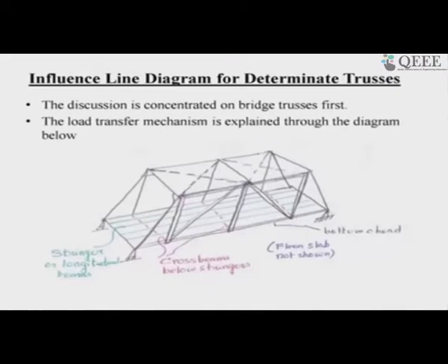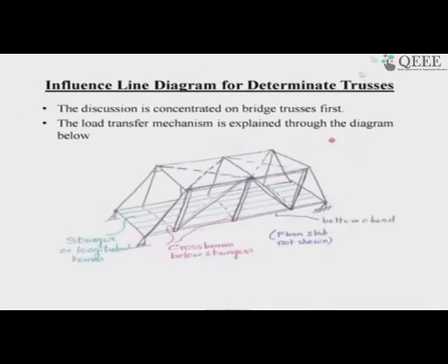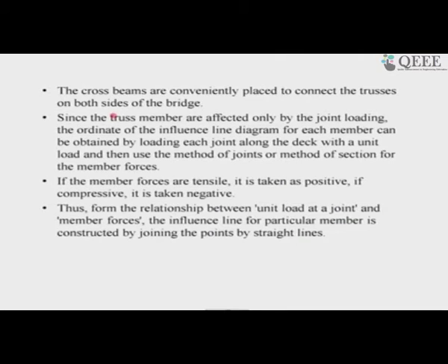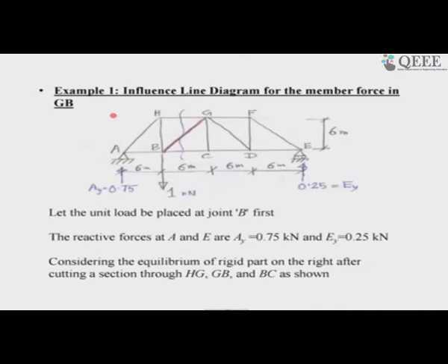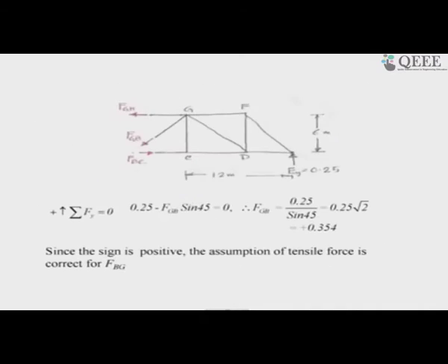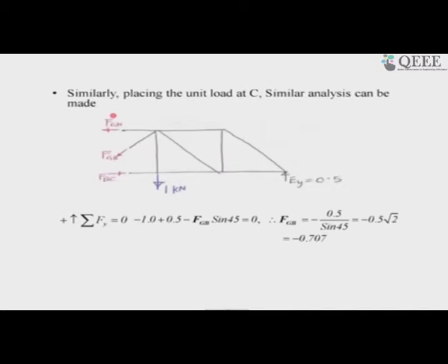This was a short session, that is why we have shifted something from the other session, and we have the truss under discussion. We have seen how traditionally by computation we can draw the influence line diagram for trusses through the solution of the trusses themselves. Since the load moves on the floor, not directly onto the truss girder, otherwise it would be subjected to bending moment. It is always subjected to axial forces.